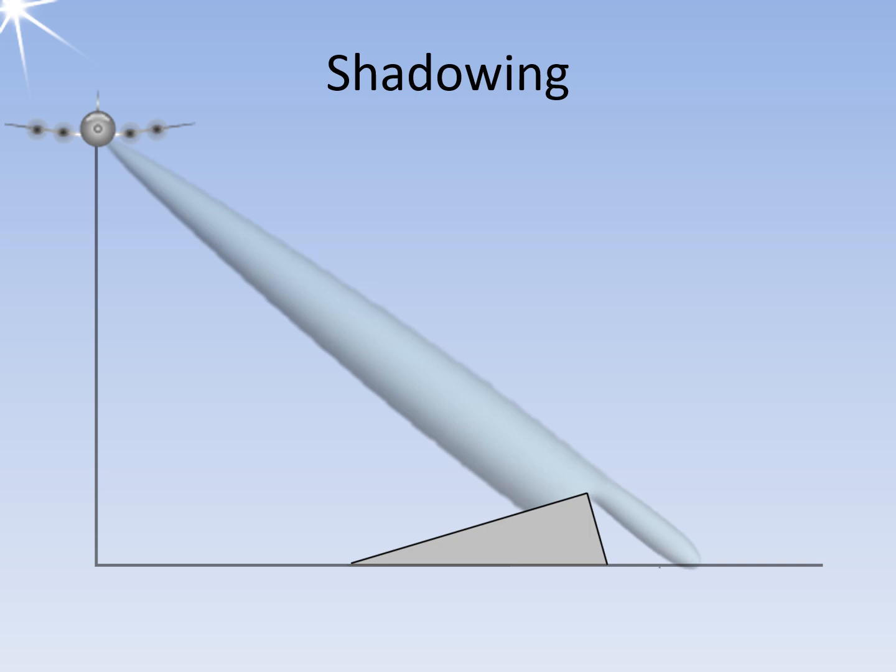Larger distances have another disadvantage: the angled illumination of terrain elevations creates a shadow effect. Nothing can reflect in this shadow, causing the area to appear dark in the radar image. The flatter the incoming radiation, the larger the angle of incidence becomes. As the angle of incidence increases, the shadows of the objects become longer.